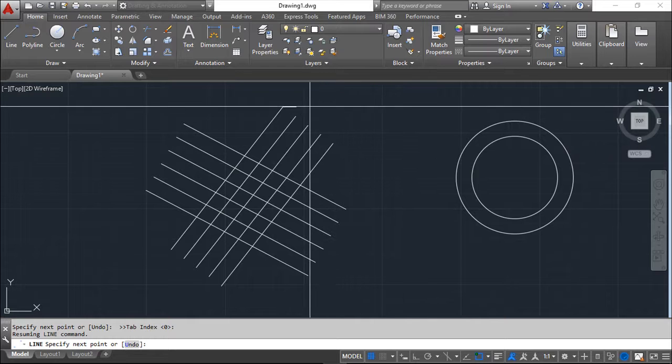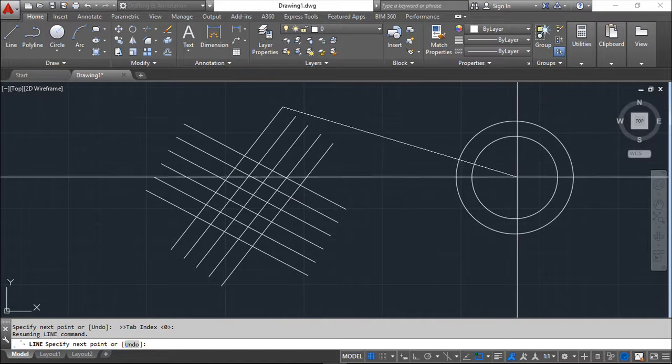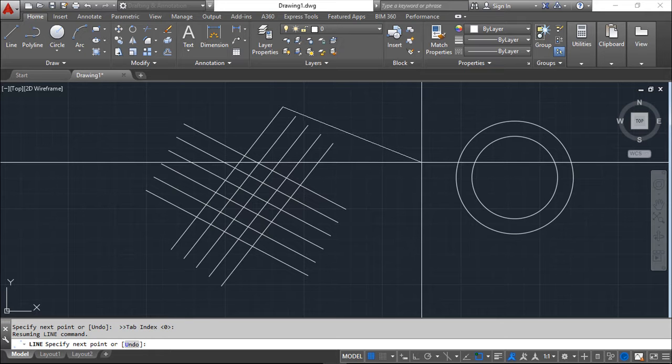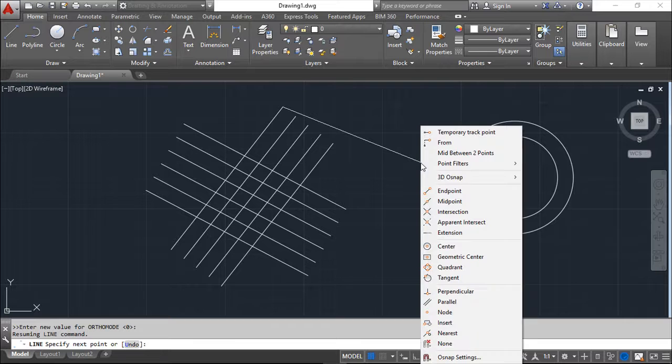So I have this done and I want to choose the center. So I click on the shift key in your keyboard, leave it and hold it, and now the right mouse button, I open this help, and the snap mode I choose is only to be used in this selection that I'm doing right after.